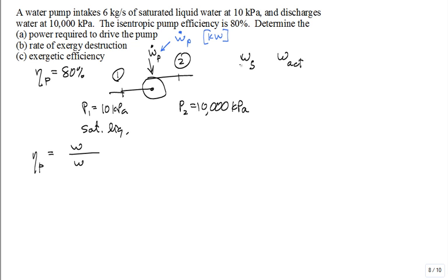Okay? So if the pump was isentropic, so there were no irreversibilities in the pump, isentropic flow through the pump, versus the actual pump, which has some friction in it. Okay, which one is going to be greater? Did I tell you already to put away the clickers? No problem. Keep them away. So we'll just take a volunteer to tell us out loud. Isentropic work would be smaller since there's less work required. That's right, because it's work required going into the system. The pump has to be supplied, so that's less. So it's going to be a funny one. Actual is isentropic over actual.